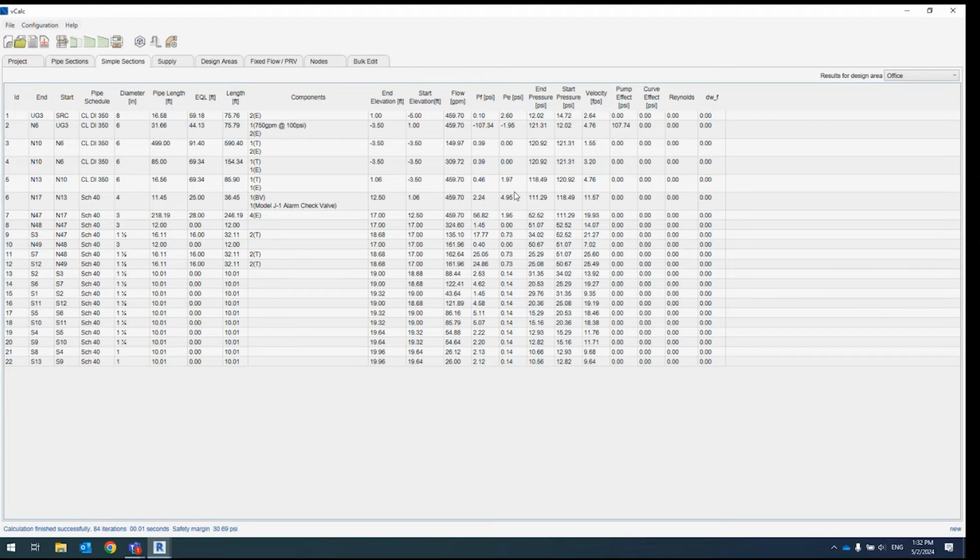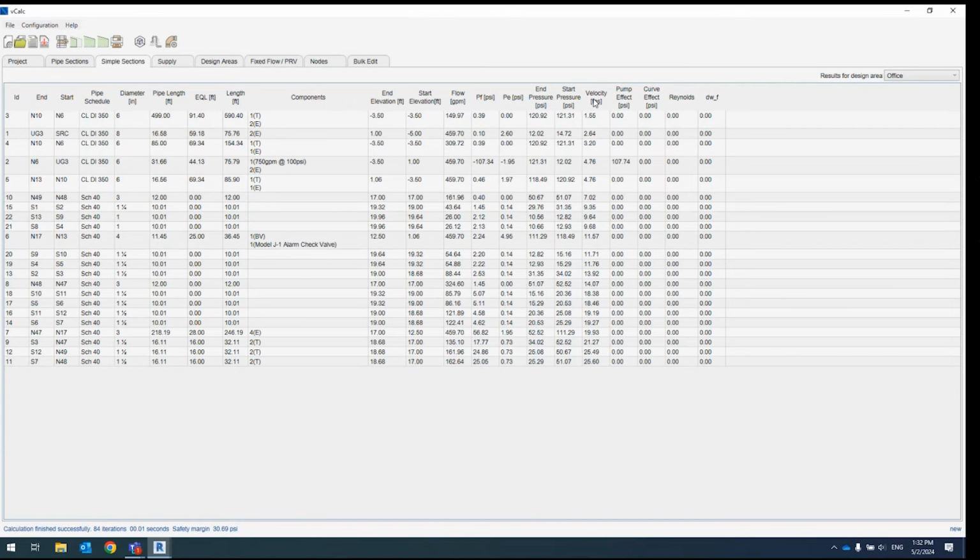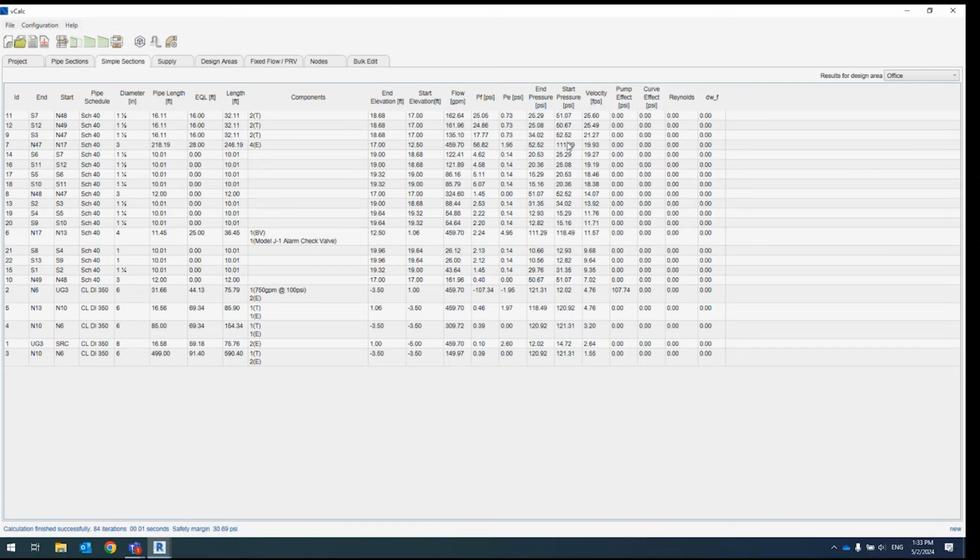And similarly to all the other tables, again, if you click on the column headers, you can sort them. So if you wanted to do a quick check on velocity, or you wanted to see where you're losing all your friction loss, you can come sort these columns, ascending, descending. That's a pretty nice way of interpreting what's going on within the calculation. So that covers kind of the first group of tabs here. Those are all the things we're kind of typically filling in the Revit environment.